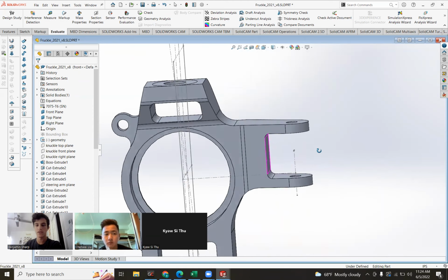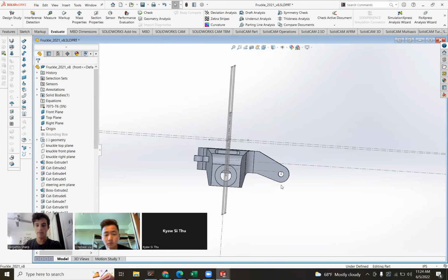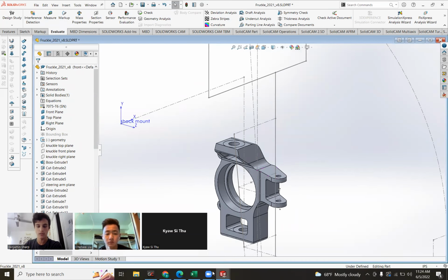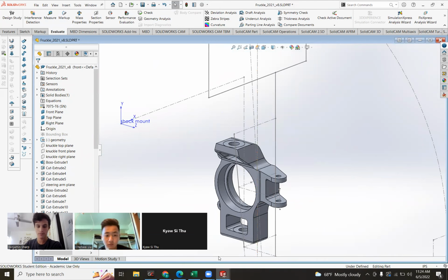And that reason is the steering force is going from the bottom to the top of my screen when you steer, and you kind of want a bit of angle, so there's more material in the load path. Otherwise it's more stress on that corner, on this corner.